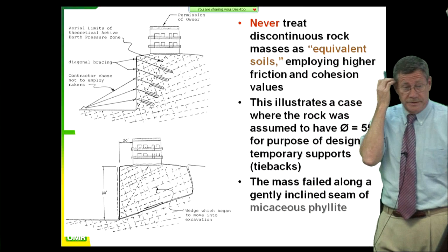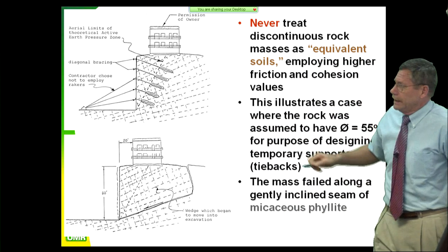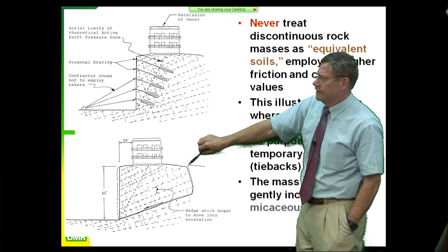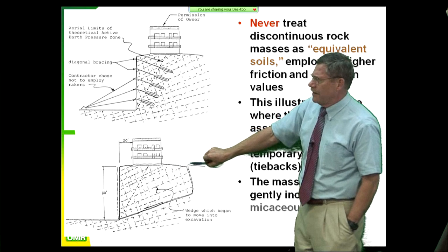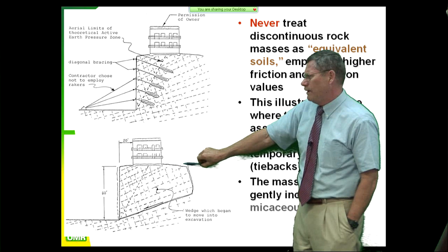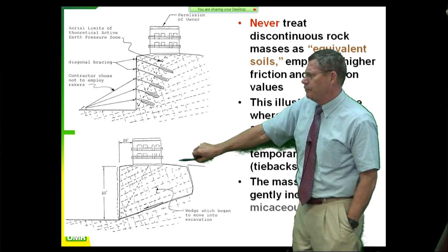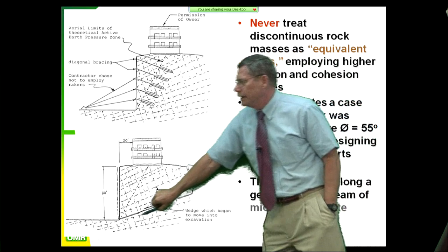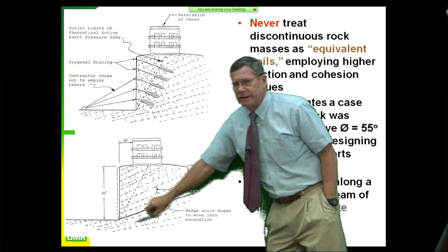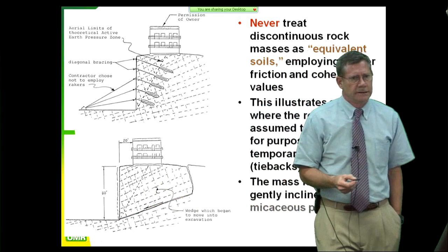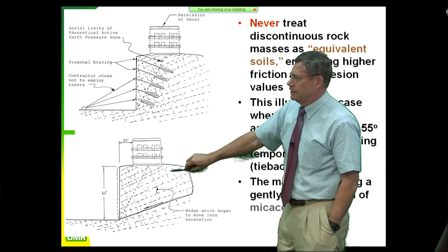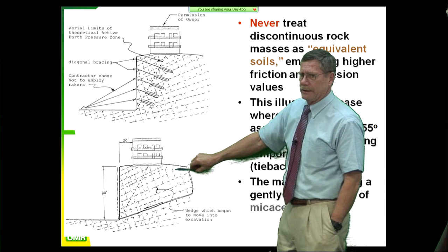So they didn't pick it up with the sonic velocity logger, and they didn't see any water coming out of the ground. The city staff, they saw there was a crack here, but they weren't worried because they didn't see water bubbling up out of the crack. Well, the water was all going down here and then down here. And by the time they realized this was a very deadly situation, you got to realize water lines are under pressure. They can leak a lot of water in a short amount of time.